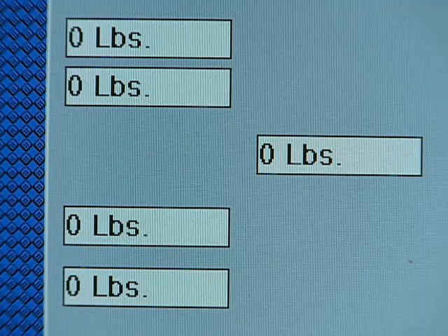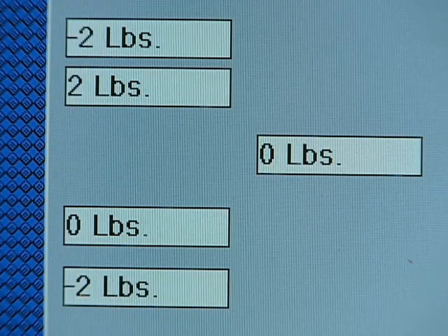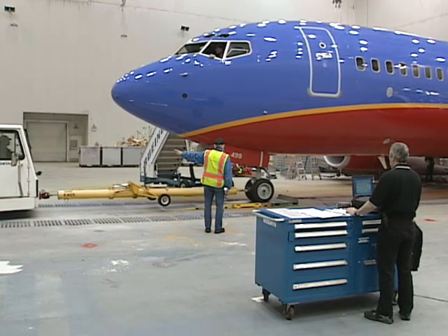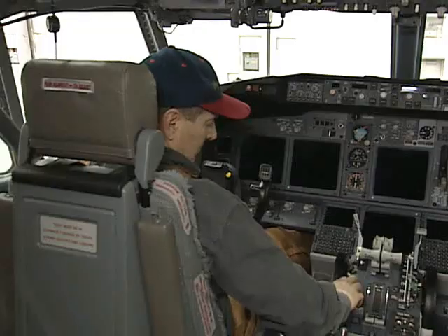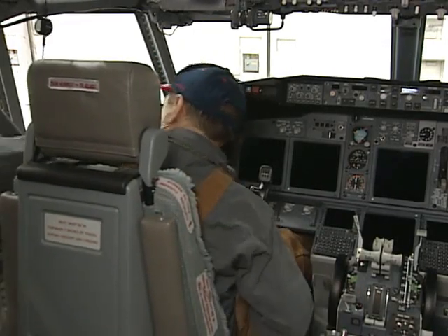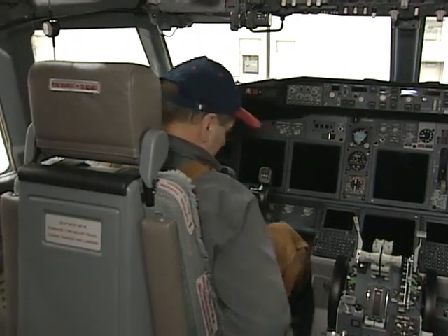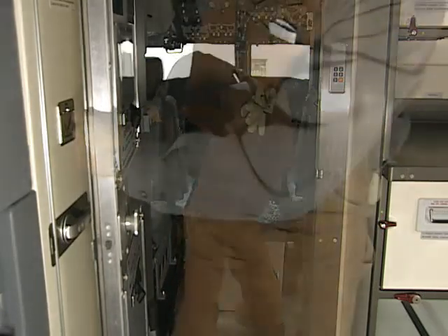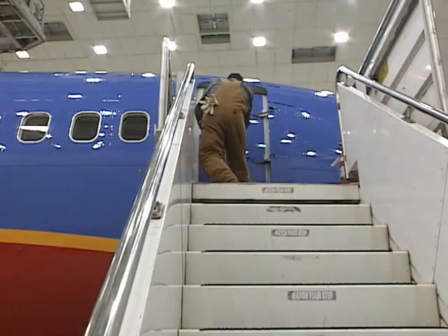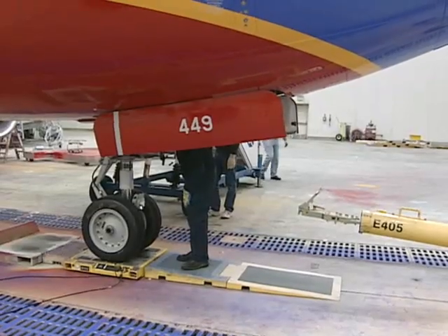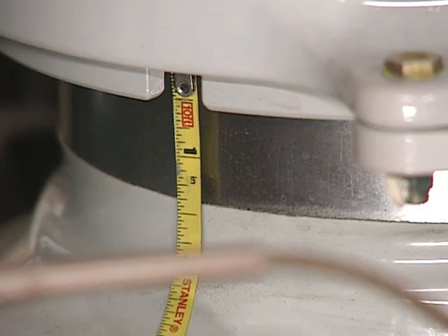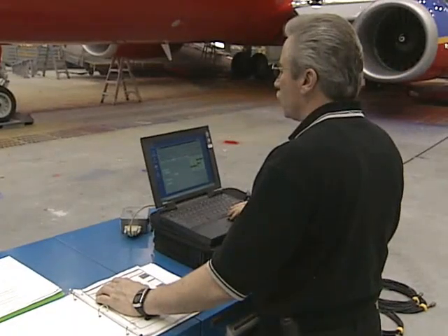Now, after releasing the parking brake, move the airplane back onto the spaces. Wait for the scales to re-zero according to the scale manufacturer's instructions. Then move the plane back onto the scales, set the brakes, and evacuate the airplane as before. Level the airplane, measure and record oleo extensions as before, and record the weights a second time. If the total weight of the airplane is within acceptable tolerance with the first reading, record the first readings and you are done with this part of the process.